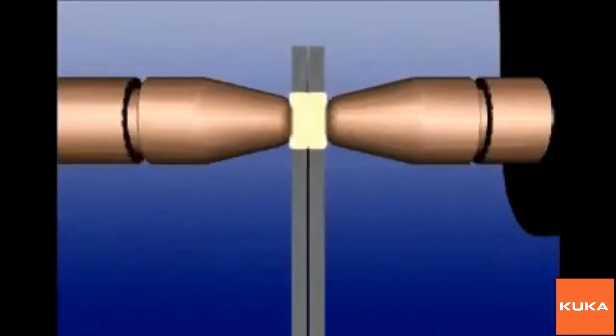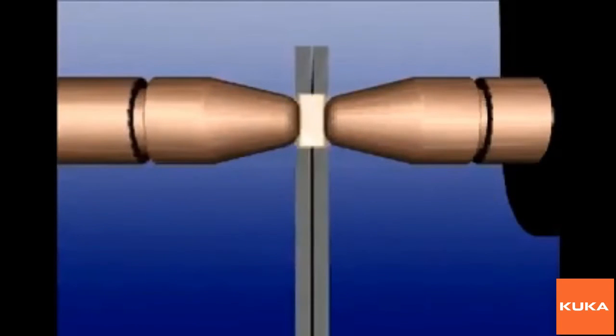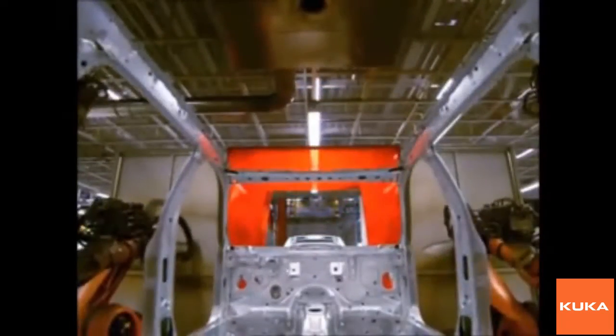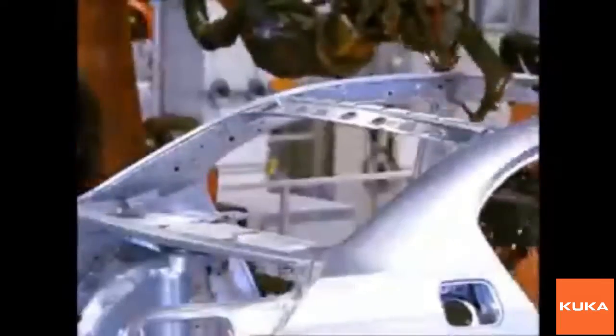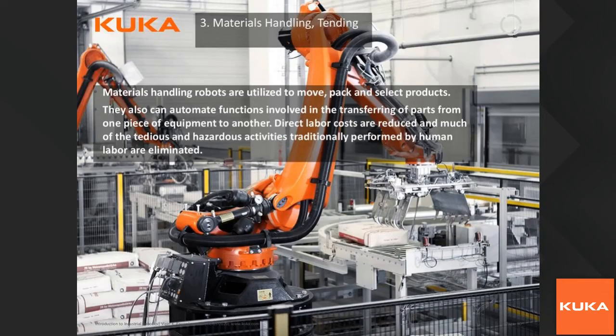Here you can see in the animation, two electrodes are pressing sheet metal. Majorly it is used for welding sheet metals like a car body. The sheet metal is squeezed like a sandwich, and current is passed in order to weld. In the picture you can also see multiple KUKA robots, some 10-20 robots working on a common car body. This is the car body in a BIW line, one of the examples from Tata Motors. You can see how many robots are working together to build a car body. This is a complete line, where one car is built per minute. This is the application we call spot welding.